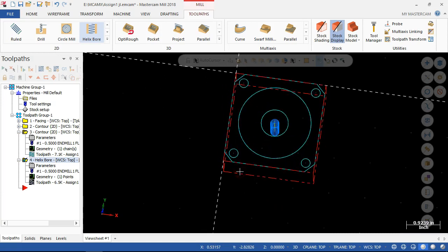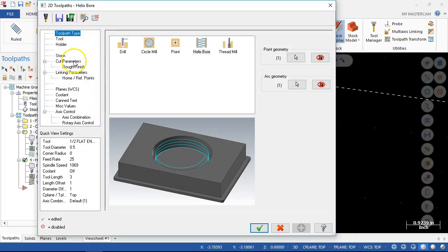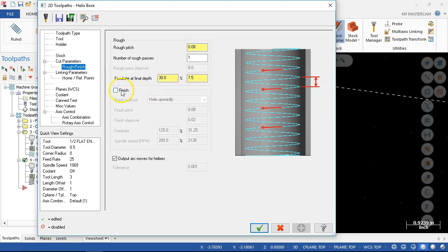That actually looks pretty good. So we left the material. So I want to pick up the same contour since I did not tell it. Well, let's see if it's available. We have the roughing and the finishing. If I can control it out of the same operation, I will, but I don't really want it to do a helix upward. I could do the circle, which is basically the same as adding another contour and saying, you know, after you get through with the helix, retract, go back in, do the contour pass, and then come up.